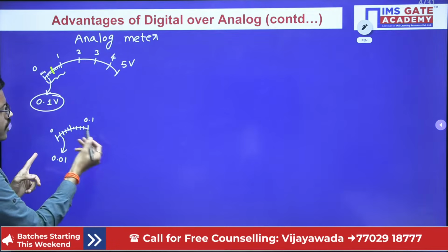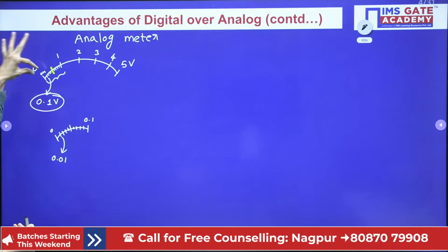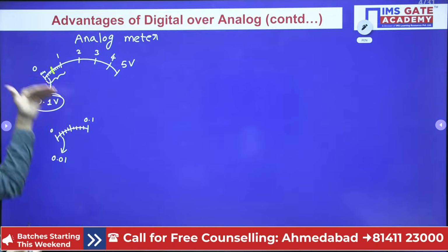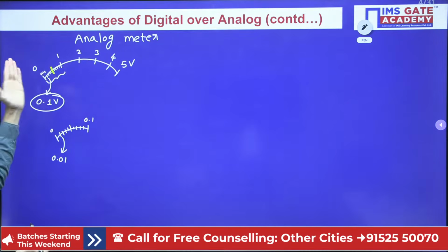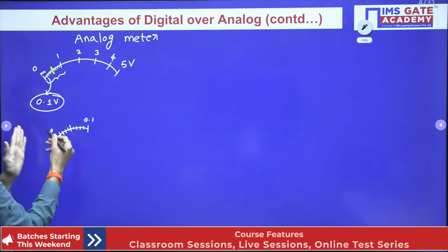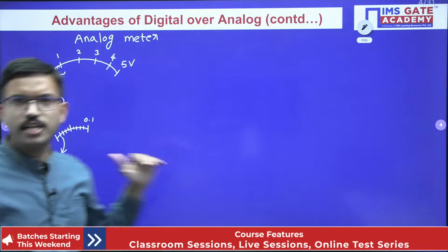But if you want to note down an accurate value in between 0 and 0.1, compared to this one, you can get more accurate because we are using one more scale. This is called recalibration of the scale. Earlier you had the scale 0, 1, 2, 3, and in between 0.1, 0.2, 0.3. And now between 0 to 0.1, we have made 10 small intervals. This is called recalibration of the scale.